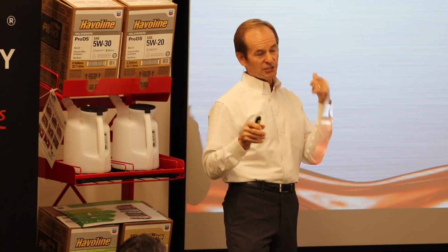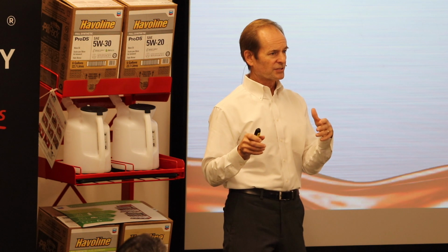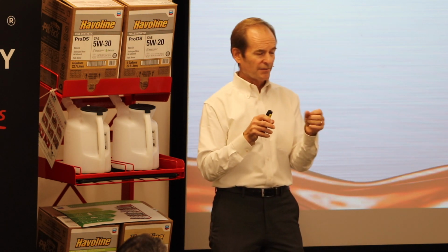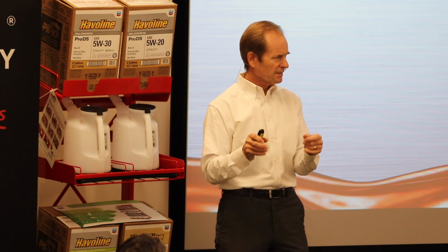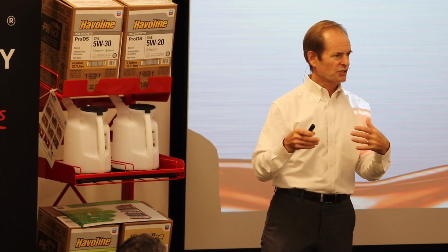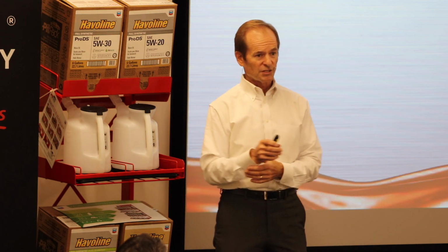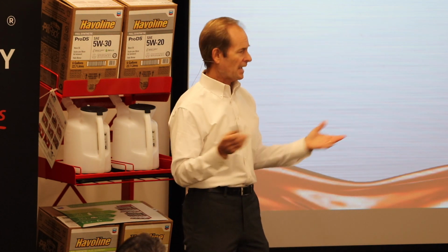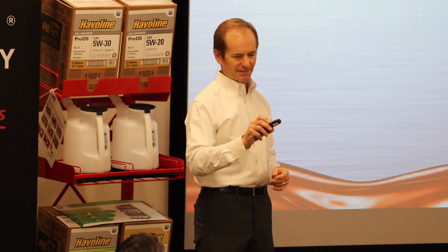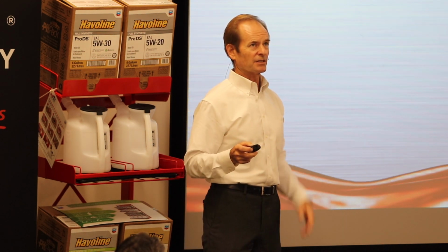Your additives actually include several of the same additives that passenger car engine oils have. Some differences. They don't need anywhere near as much detergency, and they actually have more in terms of friction modification to make for smooth shifts. And they've got red dye. Almost all of them have the red dye, right? So they do, but it does rely on additives a lot.